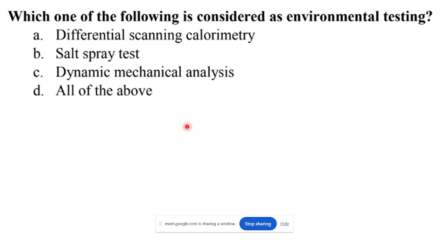Okay. So what I will suggest, based on filler loading, first of all, if you are increasing filler, your material will have a higher elastic component, and ultimately it will result in a higher Young's modulus and lower elongation at break. That is, if the material has a higher filler component. Now it's not only filler. If it is cross-linked and the cross-link density is high, again it will come to your elastic component. So there are different parameters, it's not single.